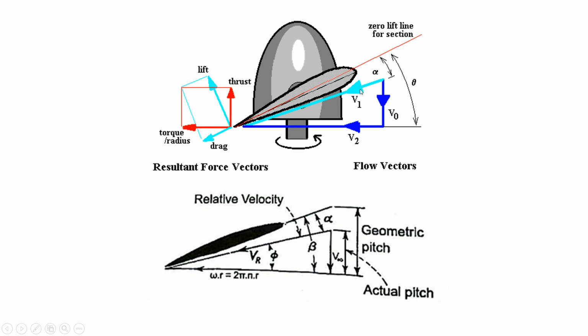And the angle of attack is produced here, from V1 to the geometric central line of the airfoil. If you take a wing, the complete angle would be your alpha, but that is not the case if you are considering it as a propeller. So this is how you obtain it. And the distance between the 0th position and your V0 will give the geometric pitch.